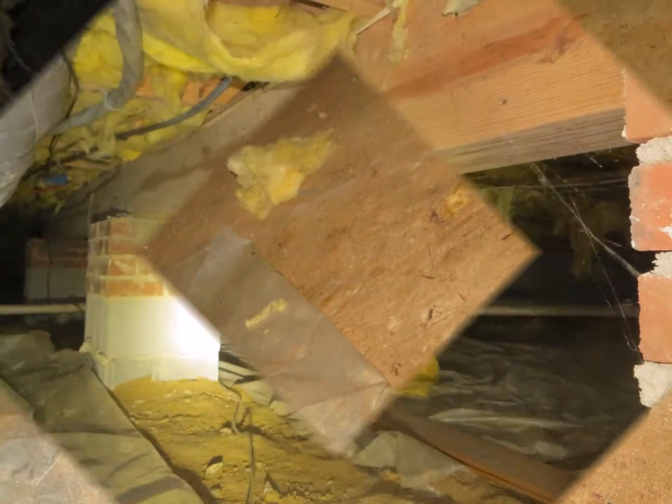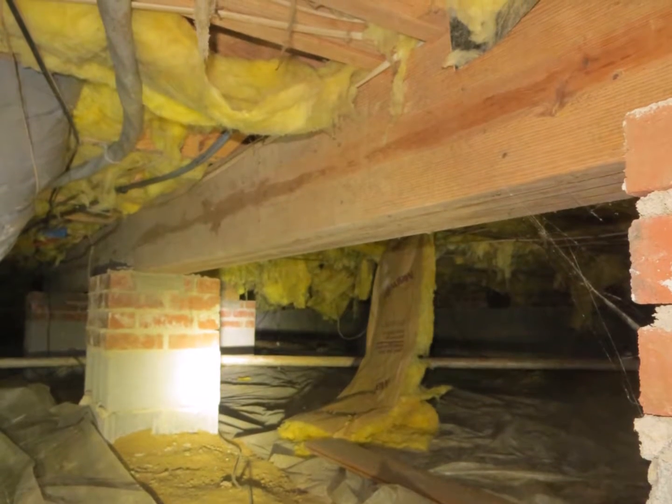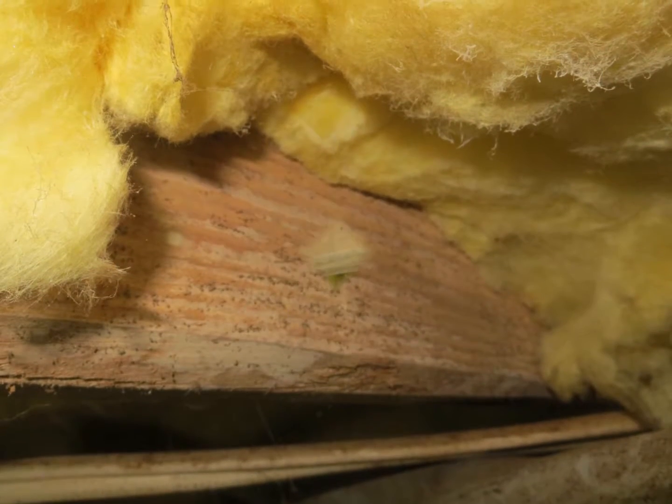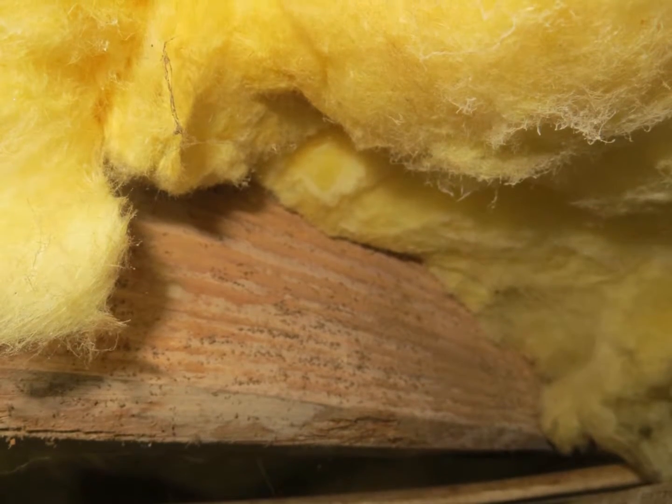There is gravel around, so maybe there's a perimeter drain in the crawl space, but the moisture barrier is incomplete and it is generating moisture. This moisture makes for high humidity in the crawl space, which causes mold to grow on pretty much all of the surfaces.